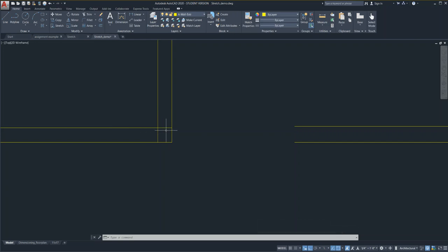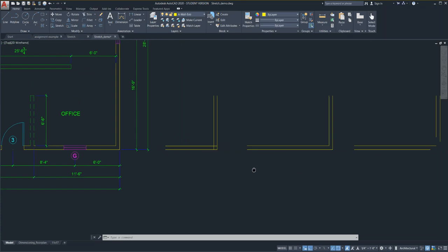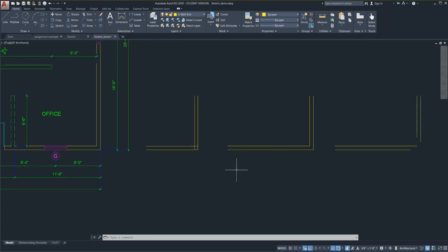And we've talked about how, you know, we need to clean those kind of things up so that they do indeed look like this, because this is the proper way that this needs to look, okay? Trim and extend, they're going to help you achieve this, all right? Now, of course, you could say, well, if I draw this with a polyline, I wouldn't have to do that. And that's correct. But you can't always draw a polyline for every single condition that you need to illustrate. So this is a really good modification tool to help you achieve what you need in a clean manner.